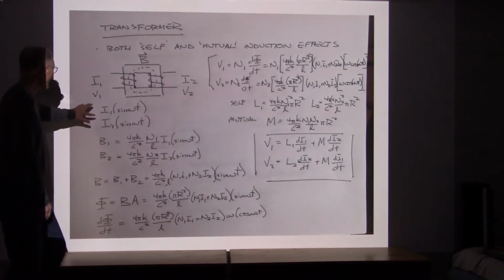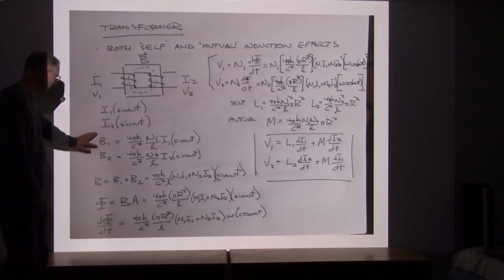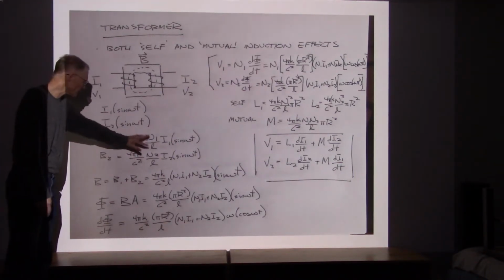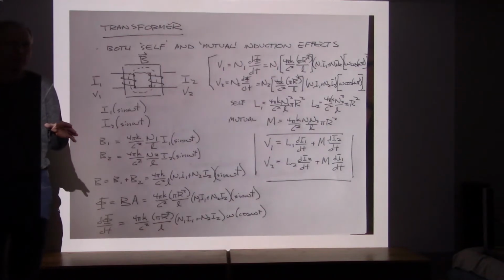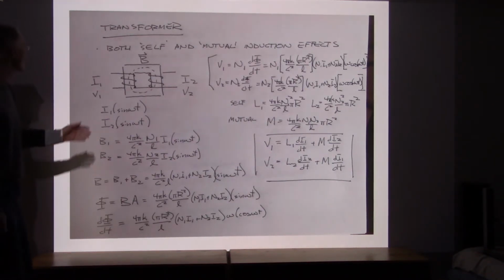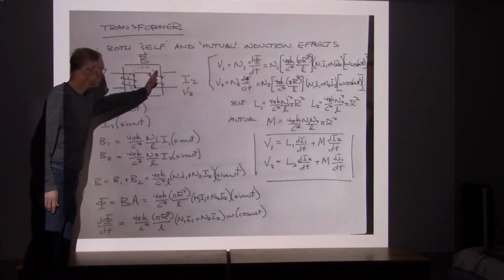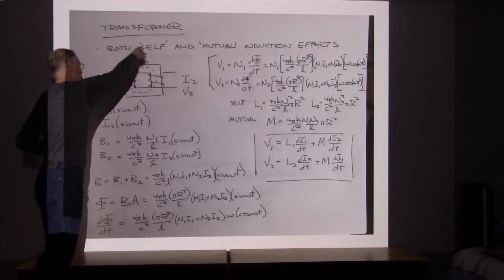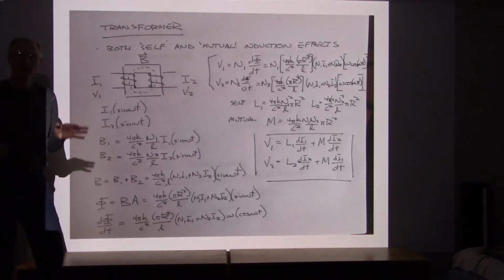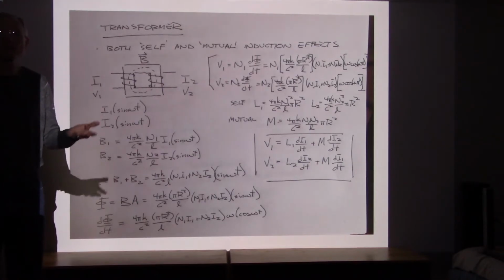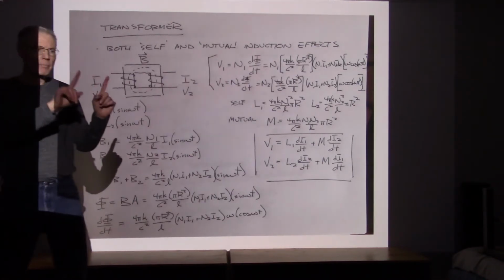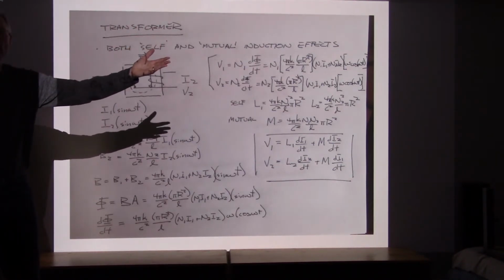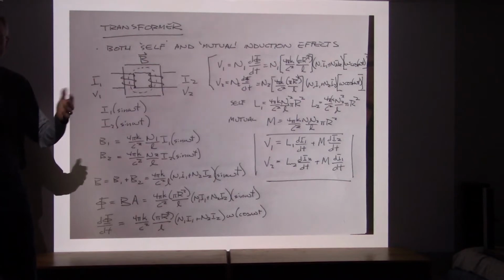Now, what happens then is that these currents are going to generate magnetic fields, and we just looked at this, so these are my formulas for the magnetic fields generated by a couple of solenoids. I've got solenoid 1, solenoid 2, they're both generating a magnetic field, and since I've got this piece of iron in here, it's redirecting the magnetic field lines so that the magnetic effects don't spread out and disappear when we get outside the solenoid.